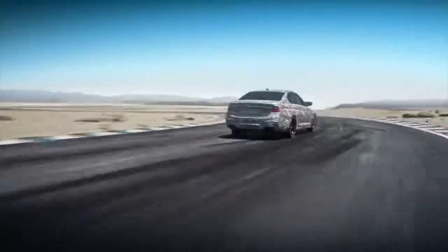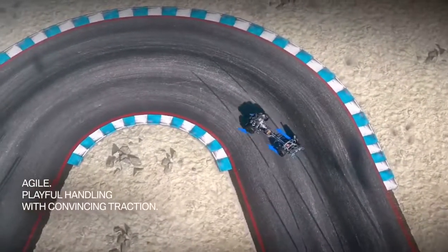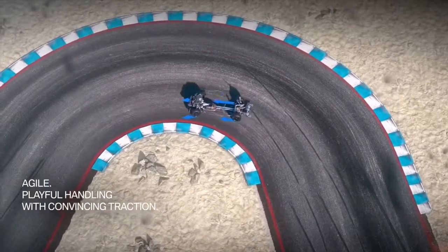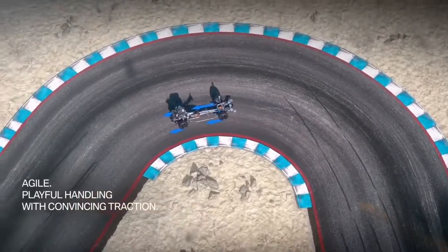So what are the advantages of each? Well, starting with all-wheel drive, one of the big advantages, of course, is that the driver doesn't have to do any thinking. The vehicle itself is choosing where power needs to go based on the traction that it's seeing. But the big advantage of all-wheel drive is that it works great both off-road as well as on-road. The reason it works great on-road is because it allows for slip within the system, so you don't have any binding like you may have with a four-wheel drive system. This means you get the performance benefits of the all-wheel drive system while you're driving on the road, specifically traction, so you can have improved acceleration.